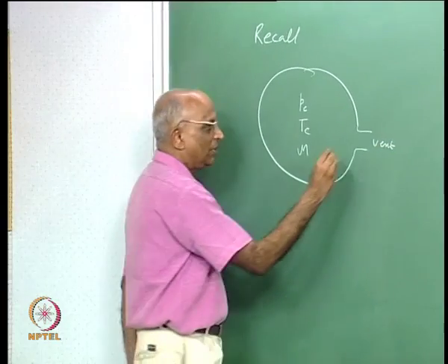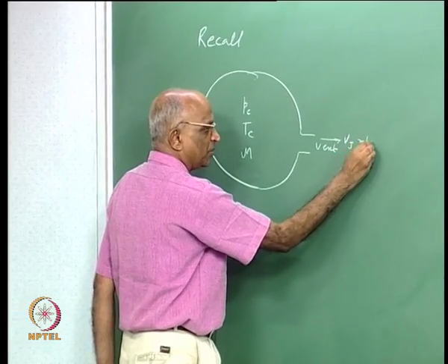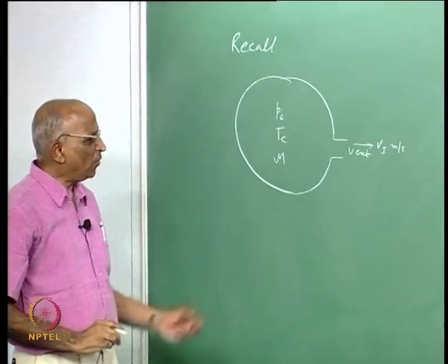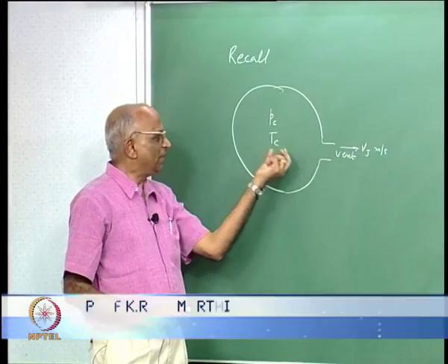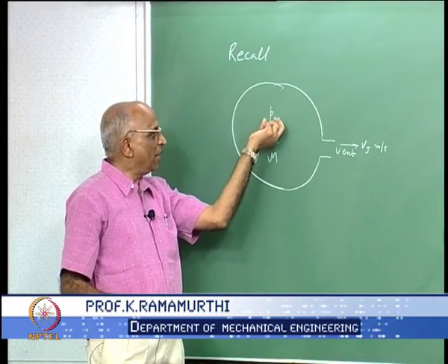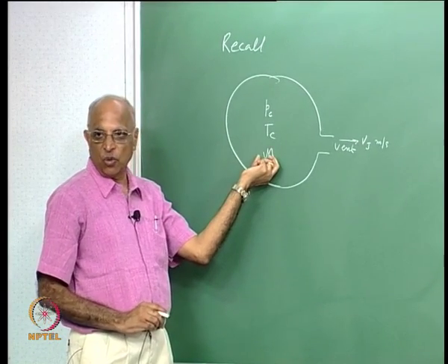We were able to calculate the exhaust jet velocity in meters per second. We found out the condition for which Vj is quite large. We told ourselves, well, the temperature must be large, the value of the chamber pressure must be large, and the molecular mass must be small.